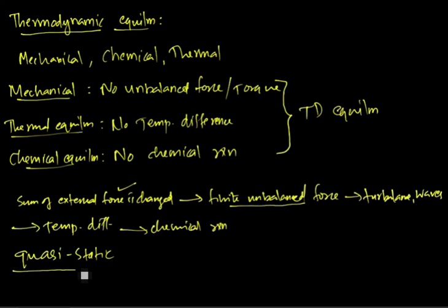So this quasi-static process is a very important concept in thermodynamics. What a quasi-static process is: the external forces are varied only slightly, so that the unbalanced forces are infinitesimal, and the system is always in thermodynamic equilibrium. So during a quasi-static process, the system at any instant is infinitesimally close to the state of thermodynamic equilibrium.